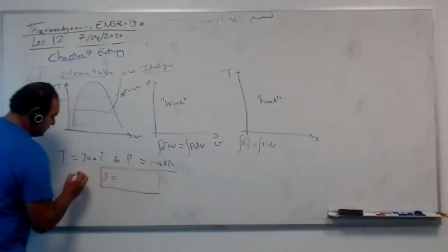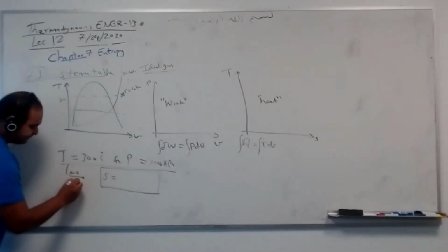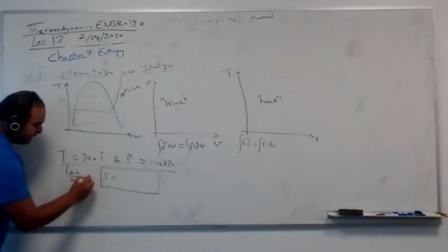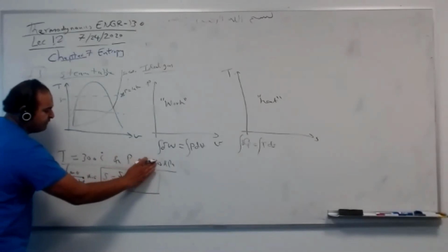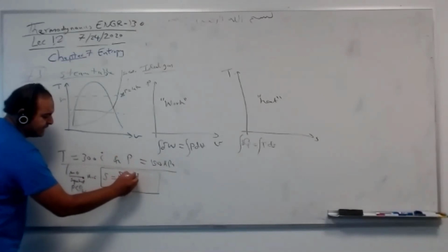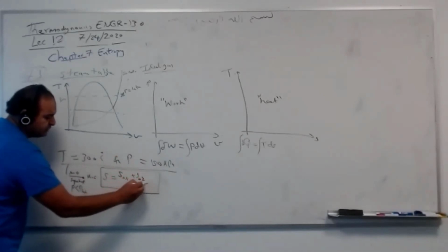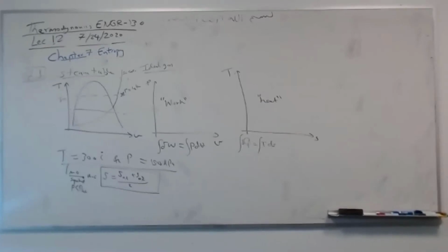So start with table A4, you will find this is superheated because your pressure is much lower than saturation pressure. Go to table A6, you'll find this value. If it's between two values, say 150, you need to get S at 0.1 plus S at 0.2 divided by 2 for interpolation. Like 8.2 plus 7.9, average them to get the S at 150 kilopascal.